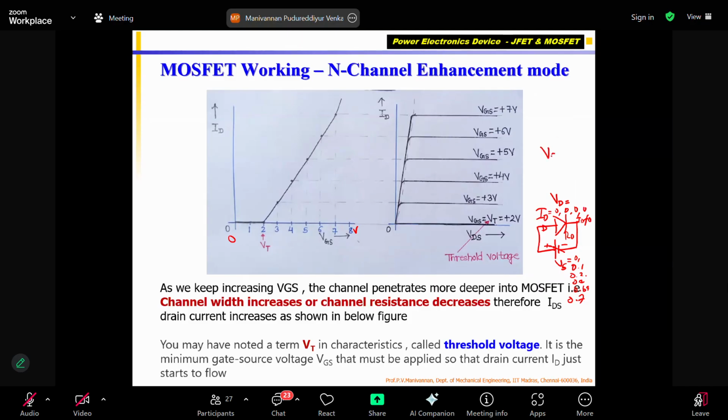When V supply is smaller than 0.7 volts, ID, the diode current flowing through the diode, is 0. When V supply is equal to or greater than 0.7, ID is not 0. How much will depend on the resistance.